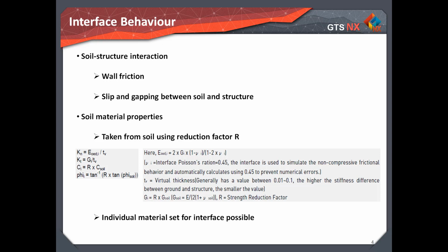The use of continuum elements with compatibility of displacement in a finite element analysis of this situation prohibits relative movement at the soil-structure interface. Nodal compatibility of the finite element method constrains the adjacent structure and soil elements to move together.